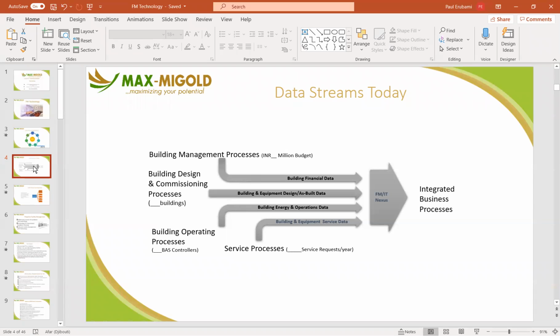Beyond that, we now have building management systems and building automation systems. Building management systems get information through sensors, feed it into a central position, and give you visibility of those data so you can take action. I can see that the CO2 level in a certain space is too high. I need to bring more fresh air into that environment, and then I activate the dampers that will open up and allow more air in through the air handling units, right? I can do that, but that's a building management system.